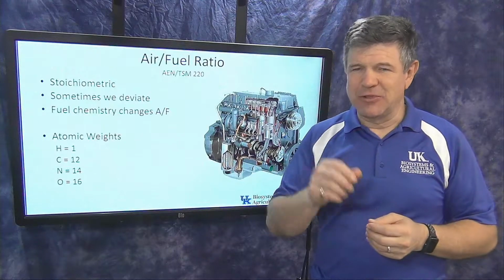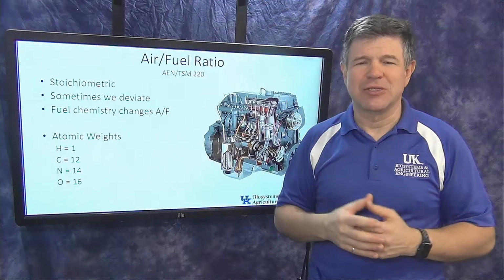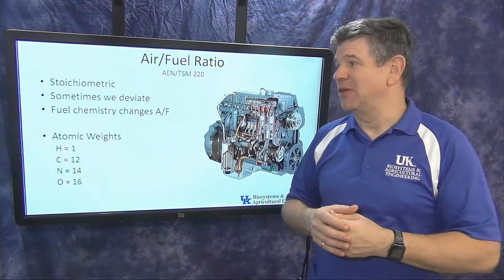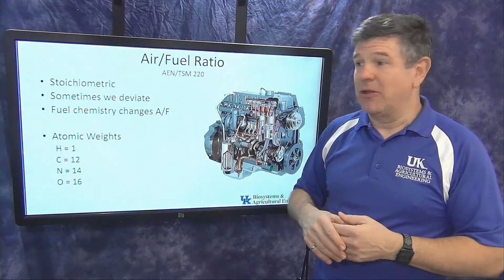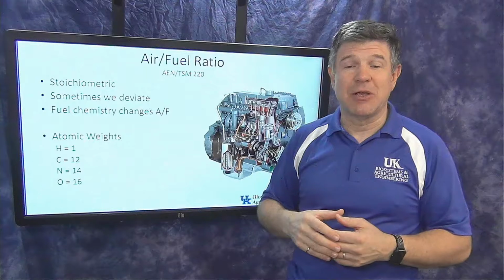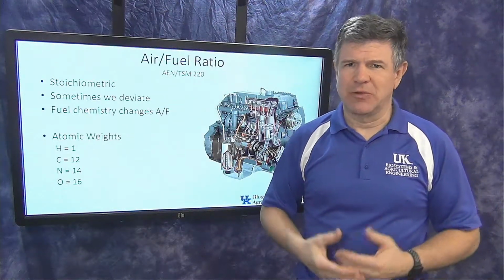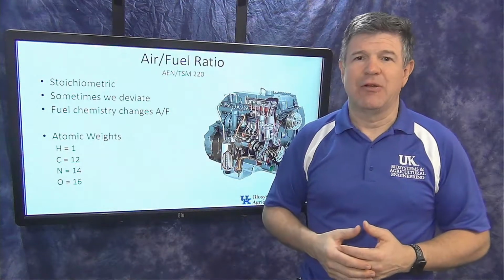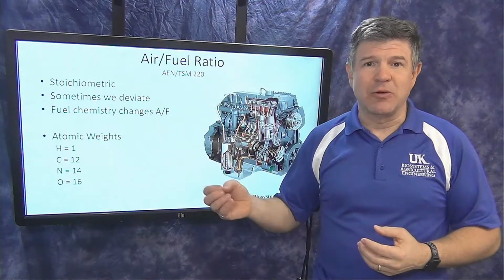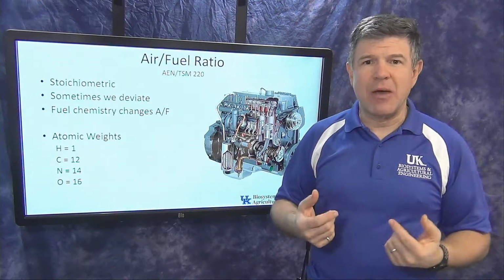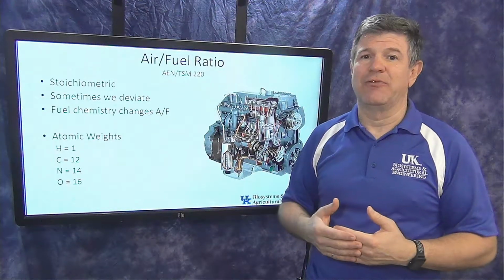And we know that, even tuning small gas engines, we'll tune the needle valve a little bit to try to make it run just as good as we can. And there can be a number of things that will affect that. So sometimes we deviate that based on emissions and all this other kind of stuff. And we're going to see as we go through here that the fuel chemistry has a big effect on what that air-fuel ratio is. And with the two examples that we'll do, we'll see that air-fuel ratio can be quite different. And that's one of the reasons why we can't just willy-nilly throw different fuels in an engine and have them operate at their best. So if we're going to change fuels, we need to change that air-fuel ratio.